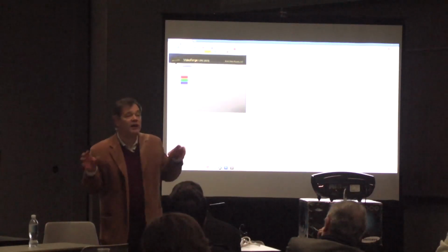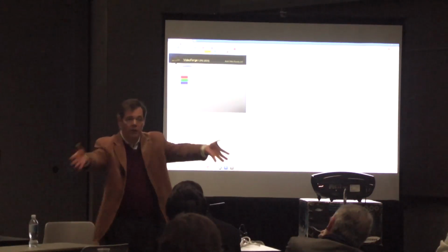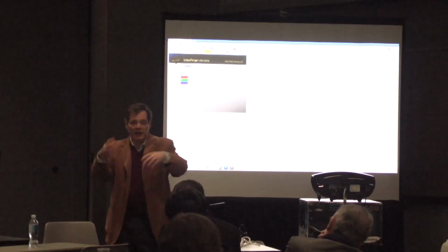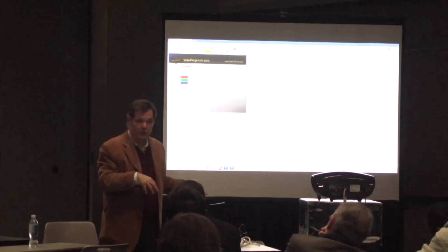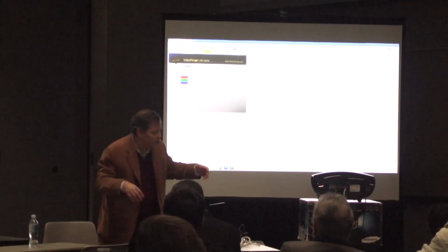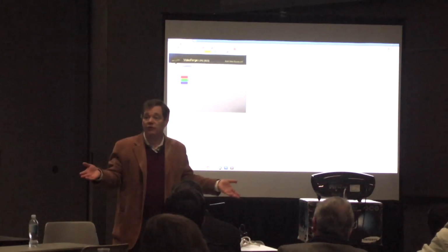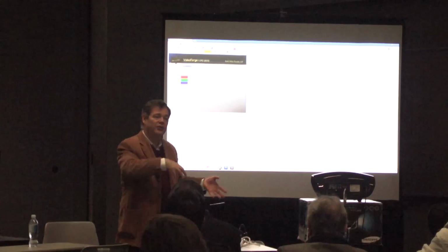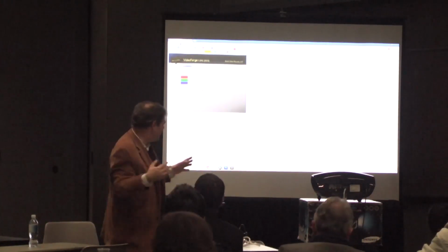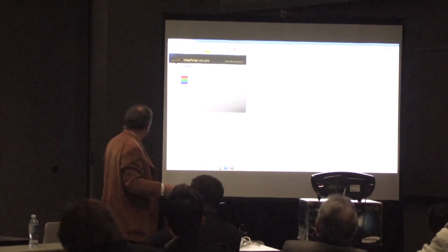So everything is transmitted in YCrCb. All MPEG encoding, all of your content is in YCrCb, and then it gets decoded and converted back to RGB. But since I have the choice here of starting out in RGB, I can go RGB to RGB, or I can go RGB to YCrCb, and YCrCb into the set back to RGB. So in this case, I'm going into the set.